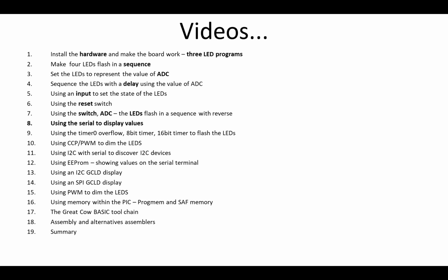We've seen the sample code, we've seen the results, it works. Okay, next what we're going to do is take this little program here, we're going to add some serial values, and we're going to send those values out to a serial terminal so we can see what's actually going on inside of that microcontroller. Using serial as a debug tool is very, very useful.